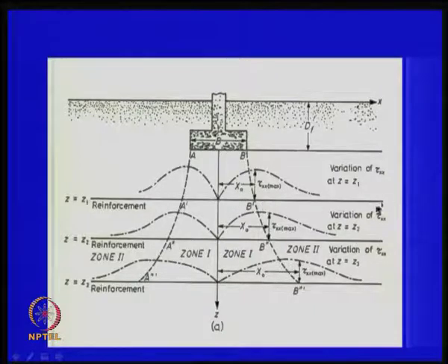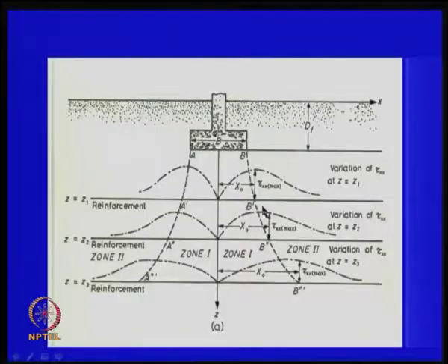Then we also have the other one, right. We need to get the total length. What is our objective? The objective is to assume some mechanics that are valid, like elastic stress distribution is valid, and we try to place reinforcement at these 3 locations. So, the requirement is that I should find out the spacing of the reinforcement, length of the reinforcement, properties of the reinforcement, like if I am using a geogrid, one type, if I am using steel reinforcement, another. Anything can be used, any member which can take some tension is sufficient here. So, you try to do that here, and then see that